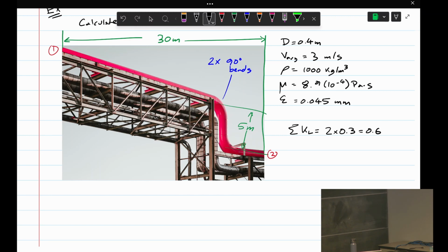In the real world, if you had a very critical part of your piping system that you were worried about the pressure drop for, you can't do the analysis through these very loose kind of coefficients style stuff we're doing. So that's where you would probably use CFD. But if you go to your boss in the real world and ask to do CFD for this, that's not a good look.